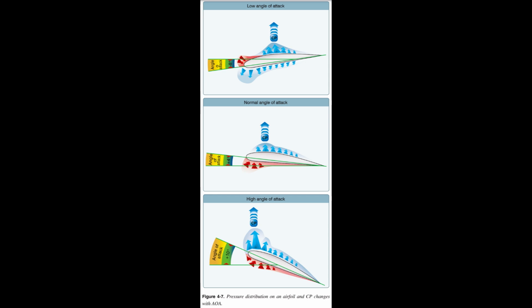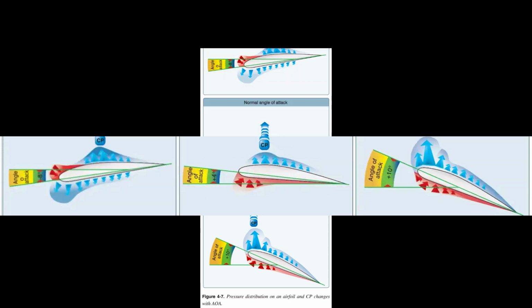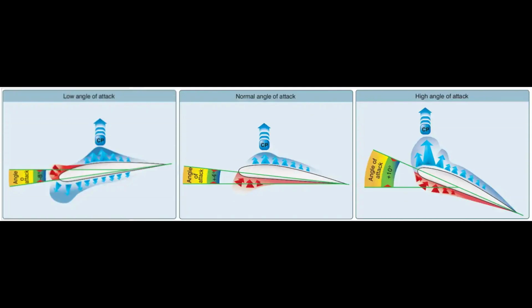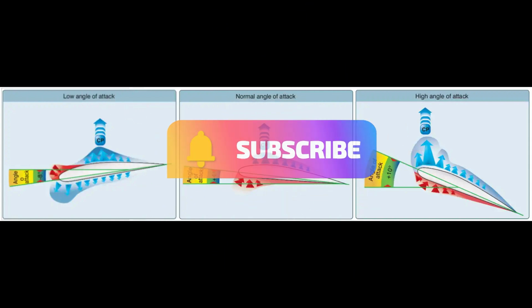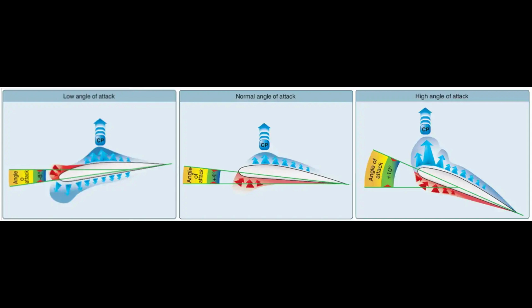Airfoil behavior. Although specific examples can be cited in which each of the principles predict and contribute to the formation of lift, lift is a complex subject. The production of lift is much more complex than a simple differential pressure between upper and lower airfoil surfaces. In fact, many lifting airfoils do not have an upper surface longer than the bottom, as in the case of symmetrical airfoils. These are seen in high-speed aircraft having symmetrical wings, or on symmetrical rotor blades for many helicopters whose upper and lower surfaces are identical.